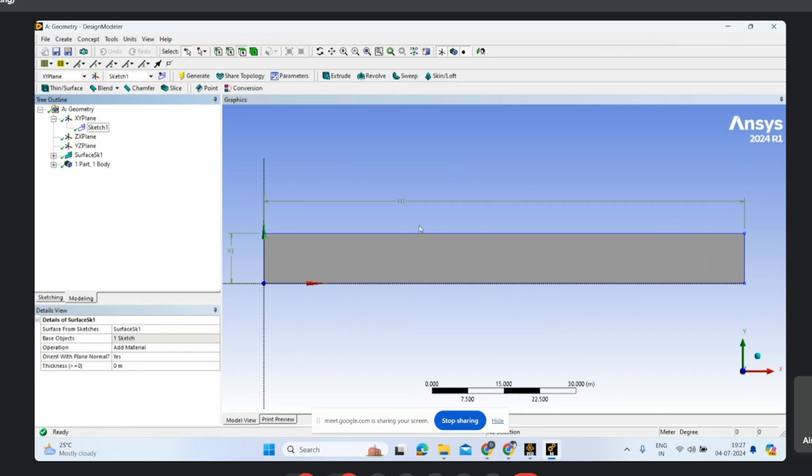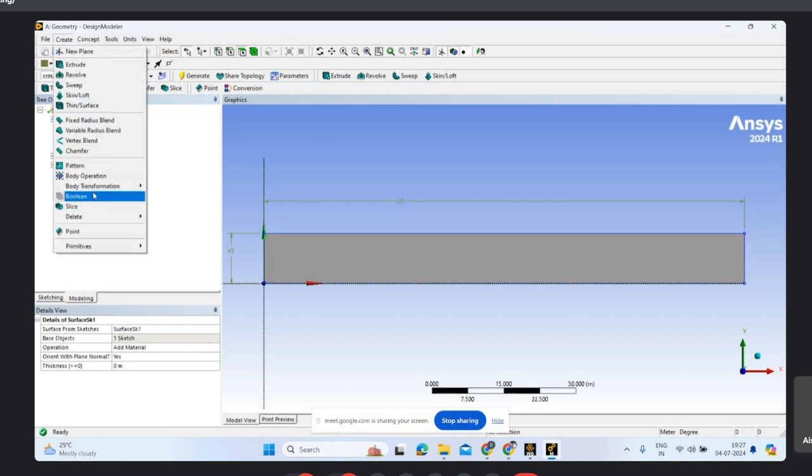And next, here we are not going to do any modifications. Suppose I want to make one more circle or a rectangle inside, I need to draw the rectangle or circle and give Boolean. There is one option called Boolean. Now there are no two different objects, no two different sketches, so no need of that.